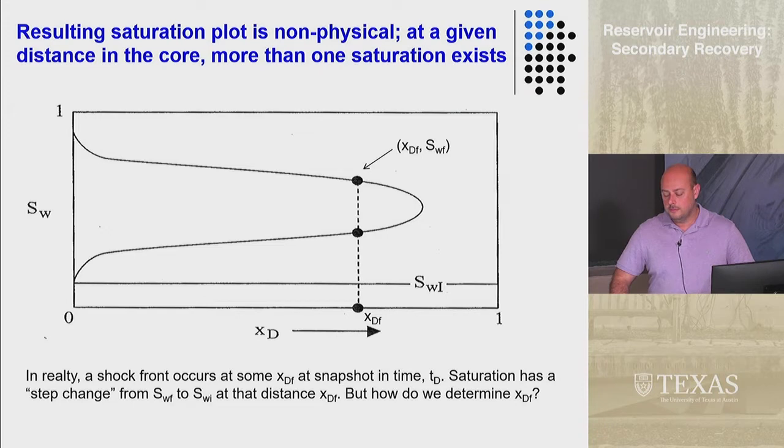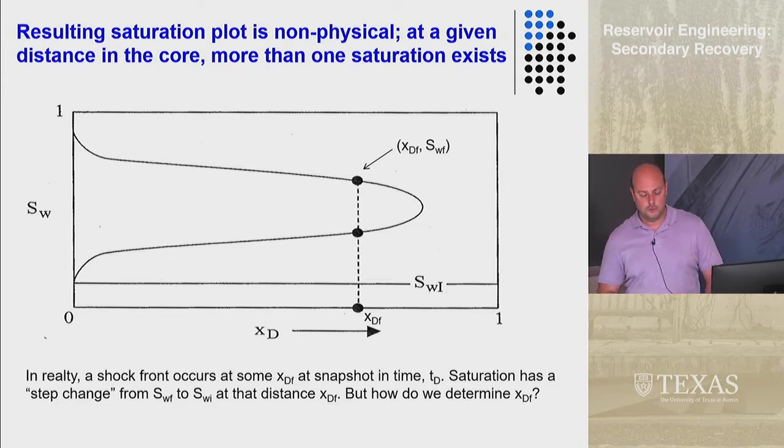They're not perfect. Instead, I would describe this shock front as a leaky wall, a wall that pushes the oil, but it doesn't push all the oil. Some of it gets left behind. So all this oil over here, okay, is oil that's left behind. We call it unswept or bypassed oil. Now, if you keep on injecting water, even after breakthrough, you will produce that oil, just slowly. Okay.